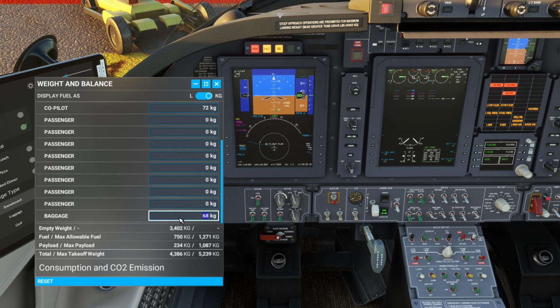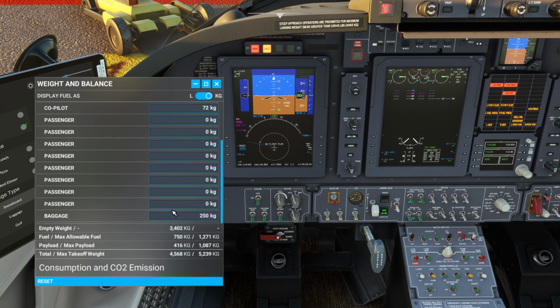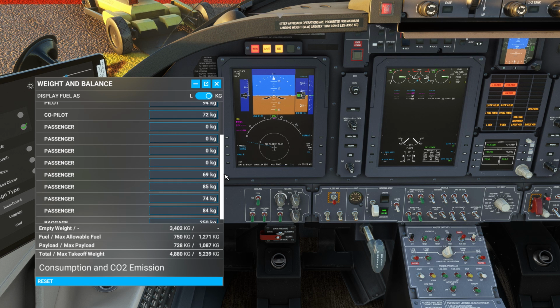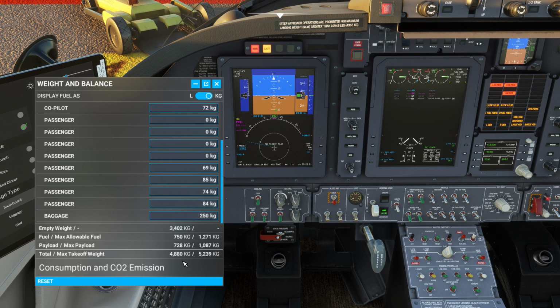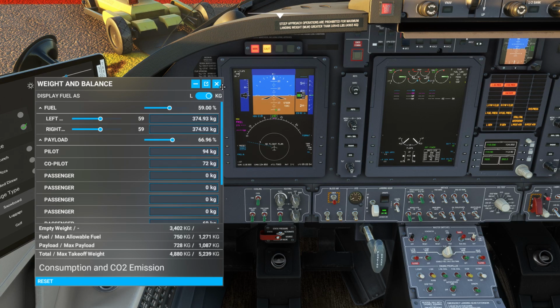Now, it is a MedEvac flight, so we need to take into consideration the equipment, the bags, the medications, all that stuff, plus the stretcher, so I'm thinking 250 pounds, the passenger, who's a male, and then a lady doctor will go for paramedic, and a nurse. That will be it. So we do have 728 kilograms on board. We do weigh 4.8 ton, which is fine.